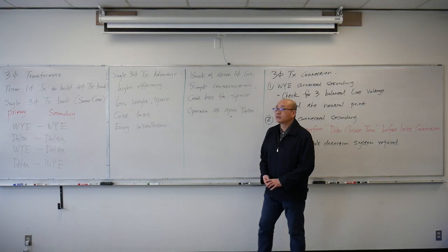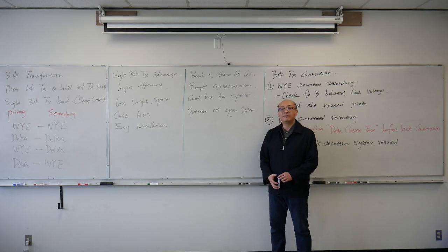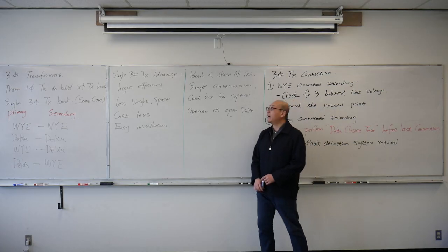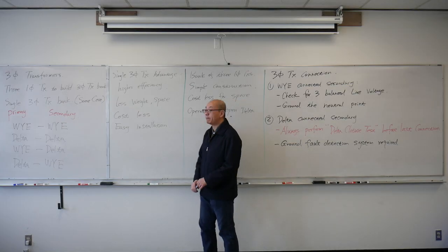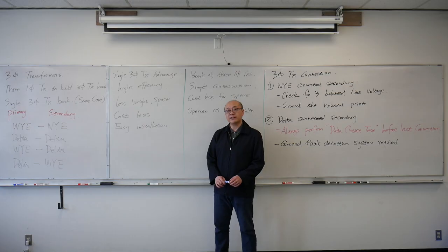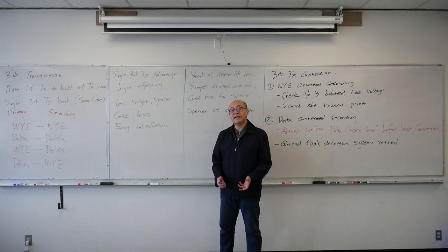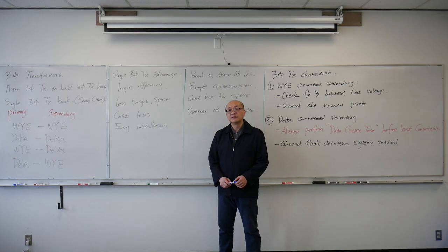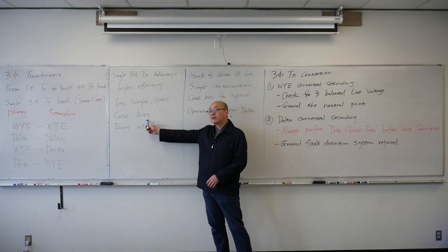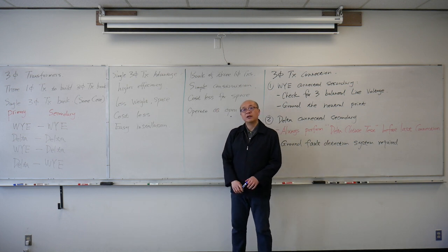Both of these three-phase transformer constructions have their own advantages. If we have a single three-phase transformer bank, it will operate at a slightly higher efficiency, and it will also occupy less space and weigh less. Also, buying a single three-phase transformer costs less than buying three single-phase transformers.